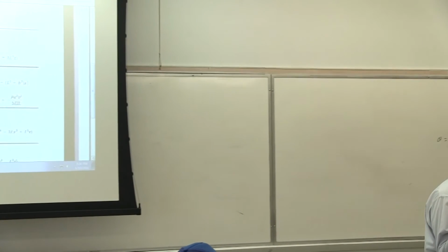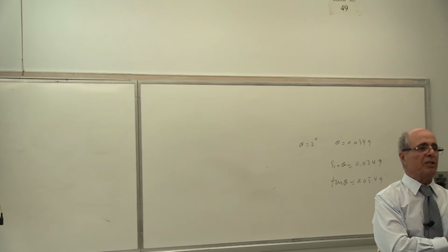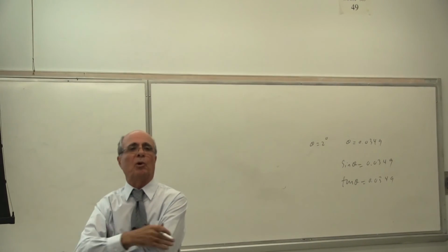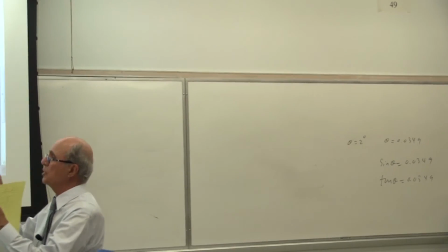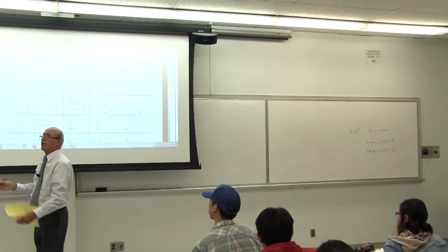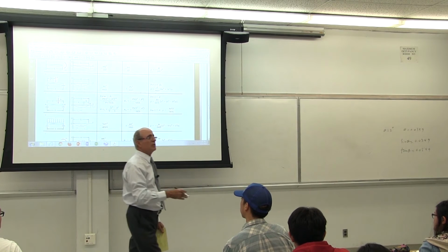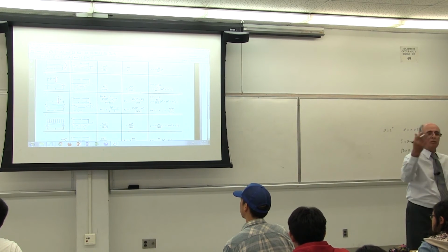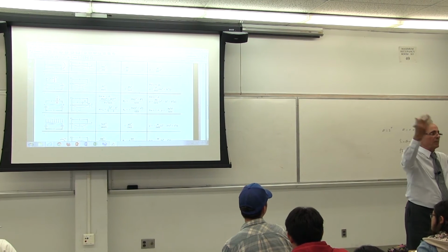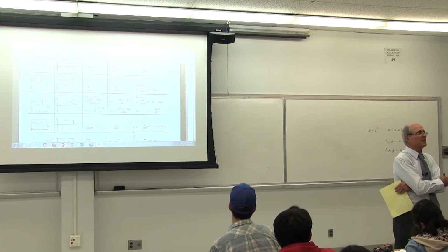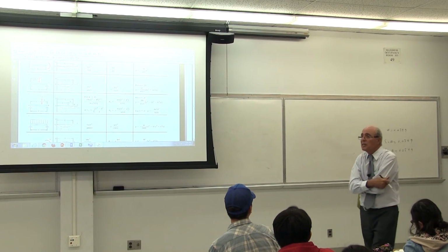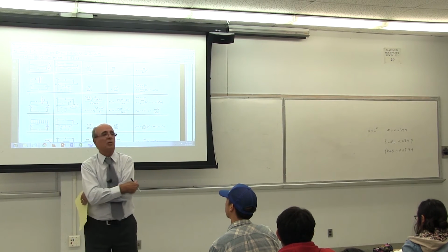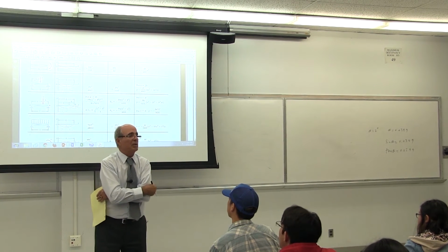Everybody understand? This system right now is indeterminate. Why? Because I just added a third support there, yes or no? Now you have 3 vertical loads and 2 equations of equilibrium, sigma Fy equal to 0 and sigma M equal to 0, so you could never find a reaction unless you do some crazy things that happened in the other class. Is that correct or not? That means that in an indeterminate problem, the static equations are not sufficient to solve it. Correct? Everybody with me?